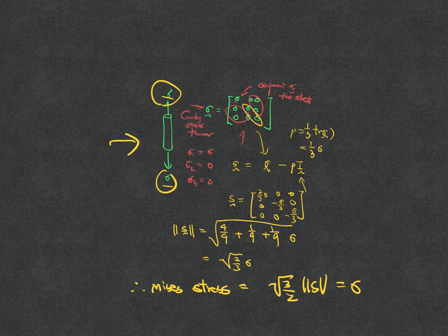Do you know why it's harder? If I want to shear the material, let's say this, I actually need to mount the material in both ways, and then I need to apply the shear. Mechanically, it's harder. You see it in soil mechanics, but then it's also more sensitive. For metal, you can apply the tensile test. This is actually a very cheap test to consider. Let me just write down the name. This is a uniaxial tensile test.